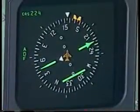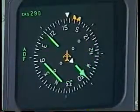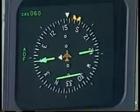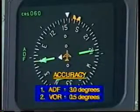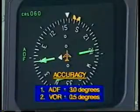The only other mode to look at with the HSI button is ADF. As you can see, the presentation is the same for VOR or TACAN. There will be no DME or ground speed available with ADF, and of course the accuracy is much less. The bearing accuracy is plus or minus 3 degrees, and your tracking tolerance is plus or minus 5 degrees. With the VOR, the accuracy is plus or minus 0.5 of a degree. All right, that covers nav mode.